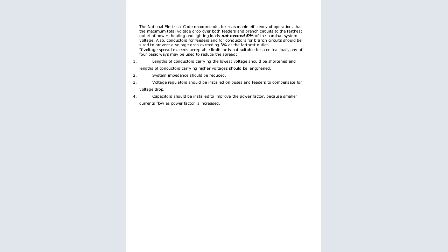You realize that, for instance, when a normal installation is being done, for example when we are wiring something like a service cable, when the Kenya Power people come to drop the cable, they normally say that the service cable should not exceed a distance of 30 meters.